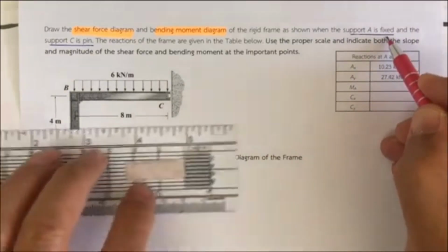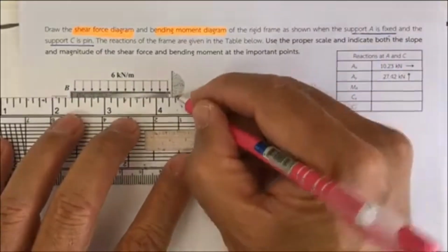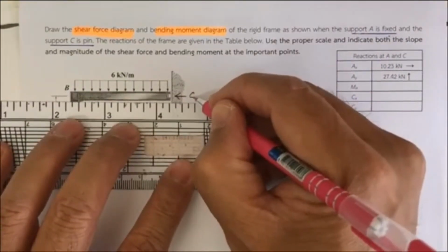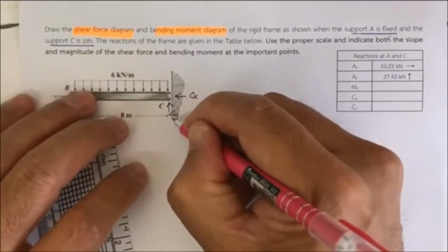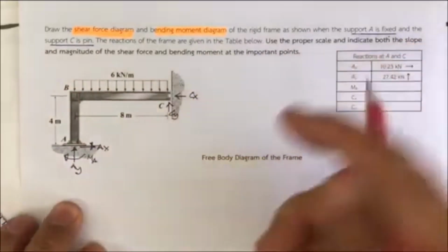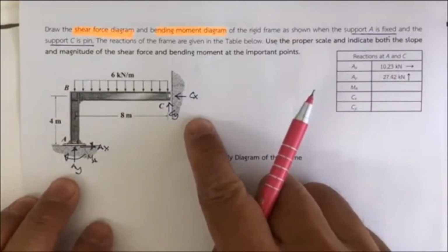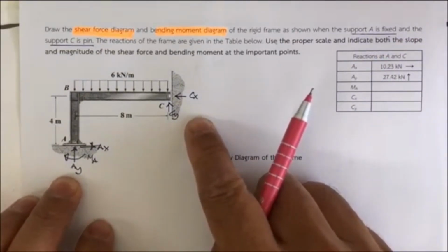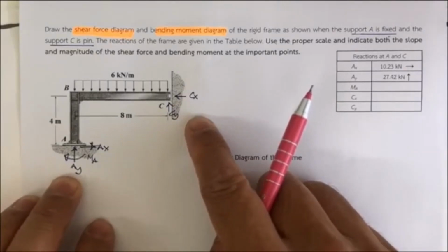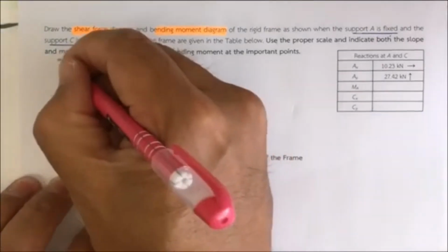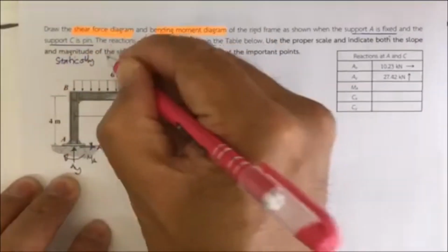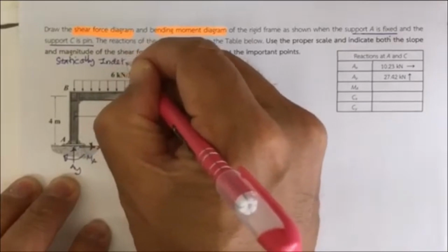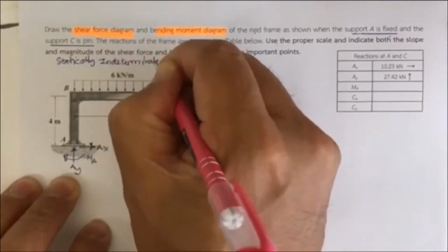And then it's going to have the reactions C sub x and C sub y here. The frame has 5 reactions, and we have only 3 equations of equilibrium for this frame. So this frame is going to be a statically indeterminate frame